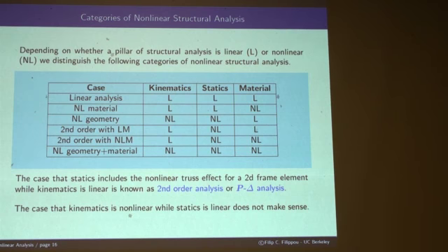What is little? Angles under 1%. Right? Please don't give me any numbers, 5 inches or stuff like that. Never do that. Just angles. Right? Otherwise known as lateral drifts, relative displacements, whatever. Whatever your choice of terminology.